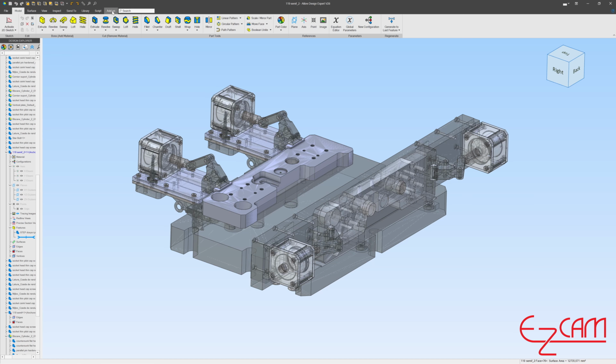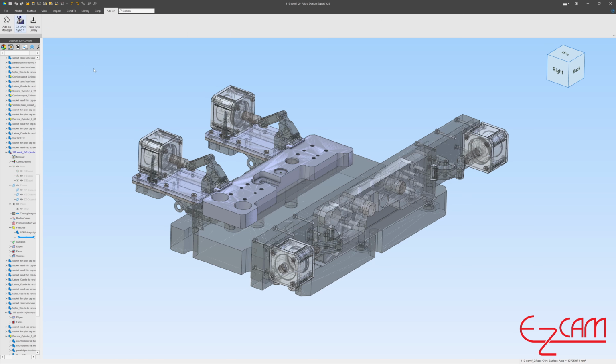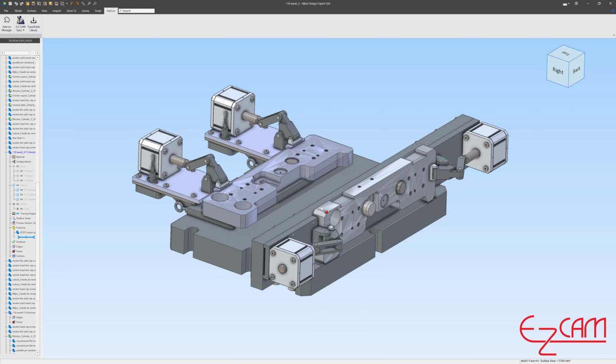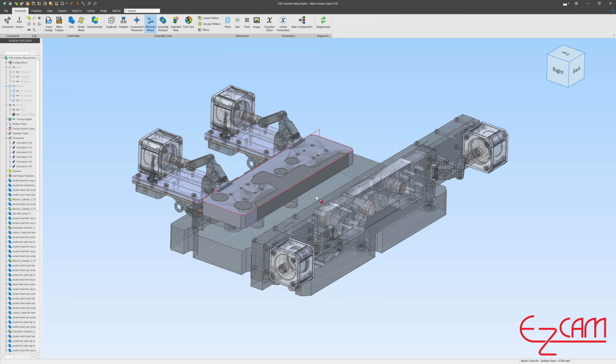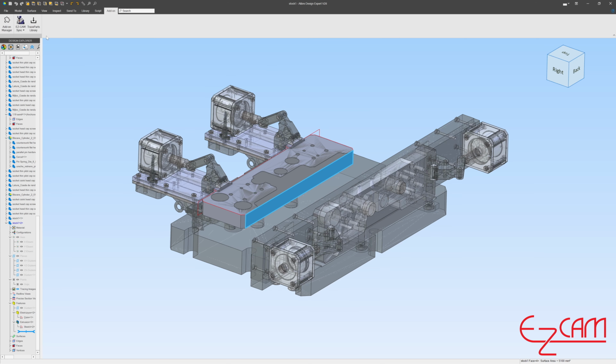Once the part has been transferred, the next step is to bring in the stock model. Right-click in an empty area and choose Edit Root Assembly. This reactivates all the components that were previously deactivated. Then, select the stock model and run Edit here. From the Add-ons menu, this time select Transfer Stock.